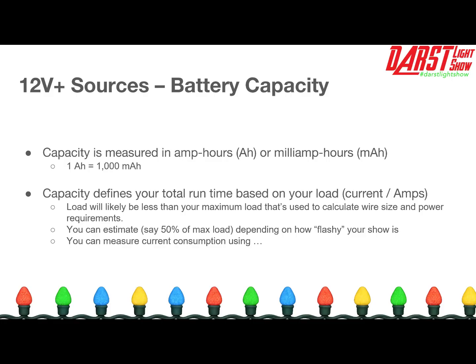Your load is likely to be less than the maximum load that's used to calculate wire size and power requirements. So we'll talk more about that in a little bit. And you can estimate, say, like 50% of max load, depending on how flashy your show is. So what do I mean? So we go through and we do all these power calculations. We talked about how many pixels can you put on a power supply? How many pixels can you put on a power converter? That's assuming, again, that you're running continuously at the pixel count at full white. Okay, you're probably not actually doing that.